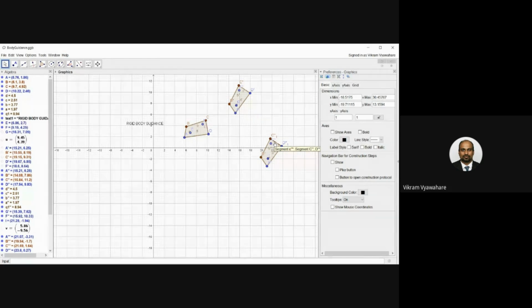A rigid body will also have an orientation, right? A point doesn't have an orientation; for a point you can have just the position. So this technique involves considering any two random points on the body. The problem will be given with just the three locations of the body visible, and then you start your synthesis. So you will have to take 2 points on the body.